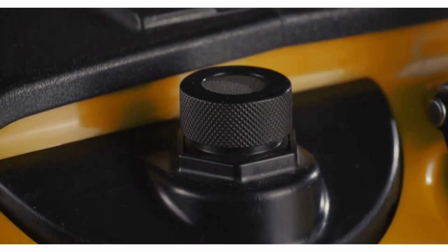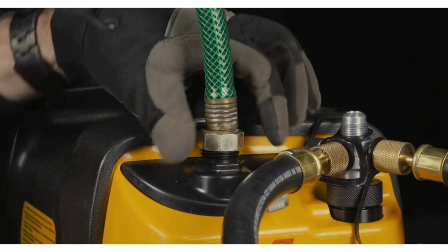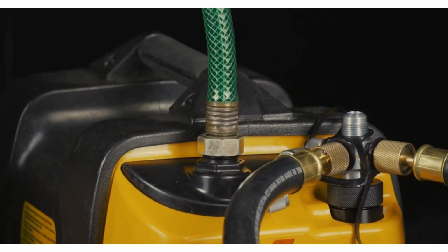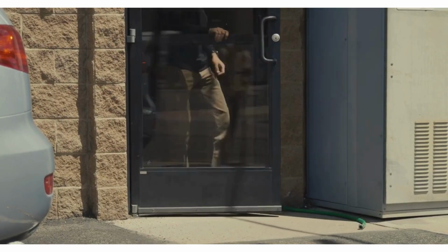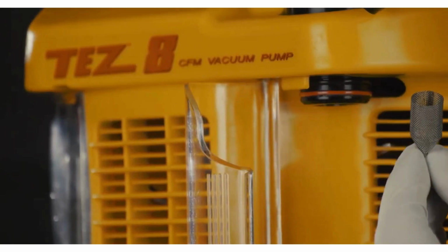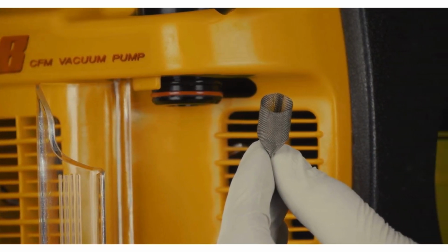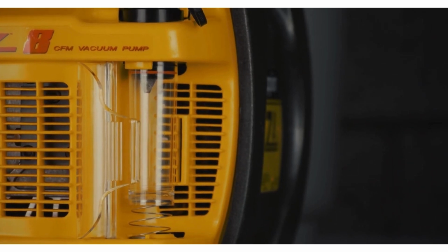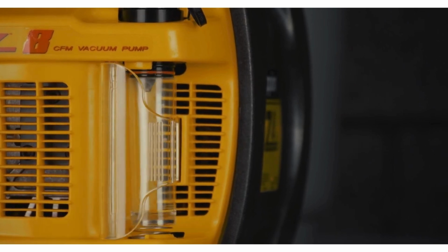When evacuating systems with toxic refrigerant or in poorly ventilated areas, use the remote exhaust connection in a common garden hose to release the pump exhaust at a safer location. The clear debris catch tube on the machine collects debris with its easy-to-clean filter screen. Conveniently, the tube traps excess oil while the patented automatic positive pressure relief eliminates accidental oil showers.